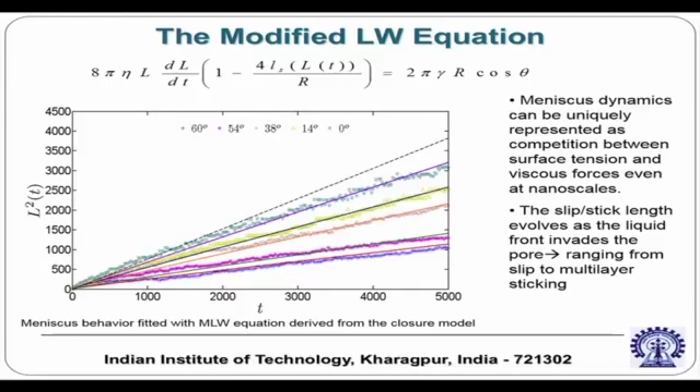So it is a modification of the continuum model, so that if the continuum model is able to get a better predictive capability, that is in turn important and interesting for using in nanofluidics applications without requiring molecular dynamics all the time, because molecular dynamics is a very good tool, but it is computationally very expensive. So the computational time is very significant and you can't simulate a large system, the number of atoms that is restricted.